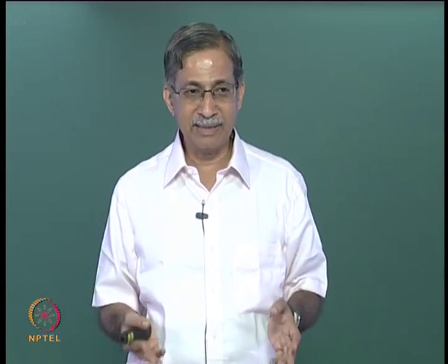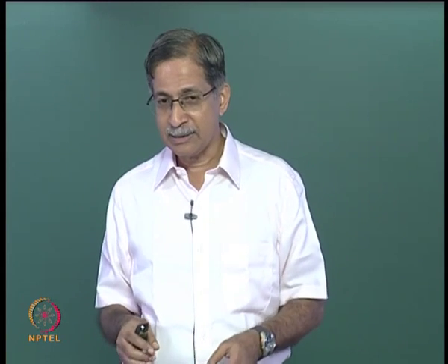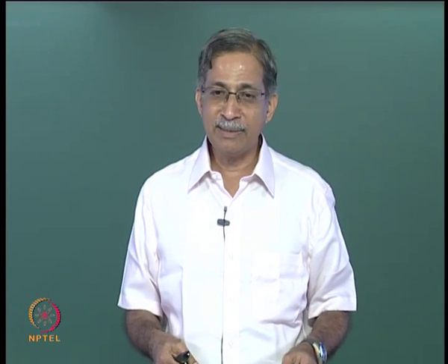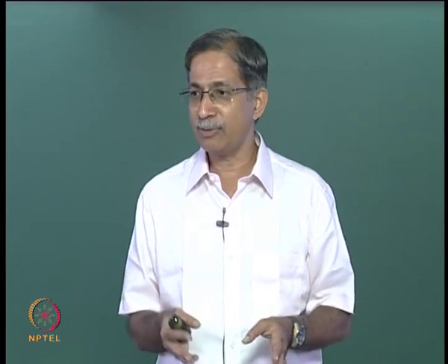It is a numerical way of solving simultaneous equations. If you notice, the superiority of the moment distribution method over the slope deflection method is that we do not calculate theta b and theta c at all, we directly get the moments, whereas in the slope deflection method you calculate theta b, theta c, and you plug those values back into the slope deflection equation.